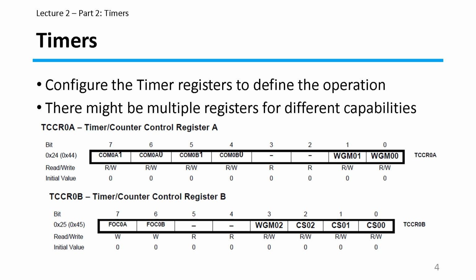Looking at the AVR architecture, you can notice that there are 2 control registers for a timer module, and each register will be in charge of separate functionalities within the timer itself. So you should refer to your datasheet to find out these control registers, and also potentially look at how the control registers are linked to your timer module itself in the block diagrams.